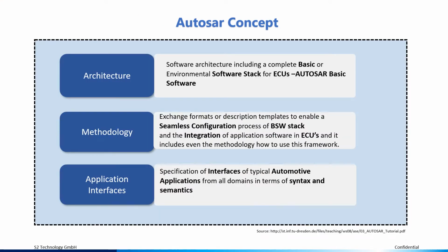The concept of AUTOSAR is designed on the basis of architecture, methodology and application interfaces. In architecture, there is the software architecture including a complete basic and environmental software stack for ECUs, the AUTOSAR basic software. Methodology covers the exchange formats or description templates defined by a BSW stack, and how the integration of software needs to be done, which is defined by the AUTOSAR concept, so we call it the methodology.